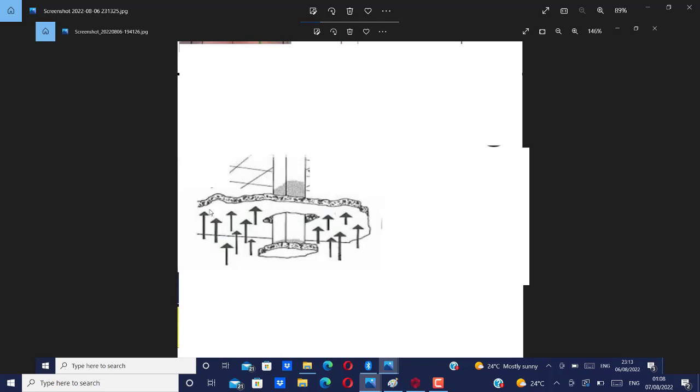Can you see how this column punctured through this slab? Because the thickness of this footing wasn't sufficient. You can see the area through which the thing punctured and passed and made a hole. So this one will give us a total collapse.